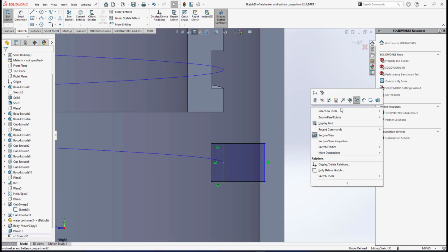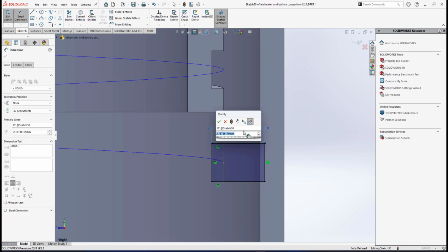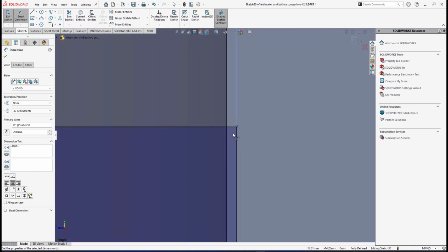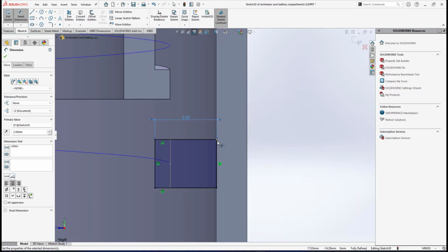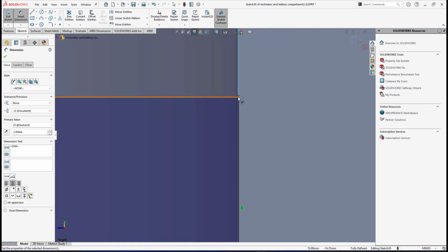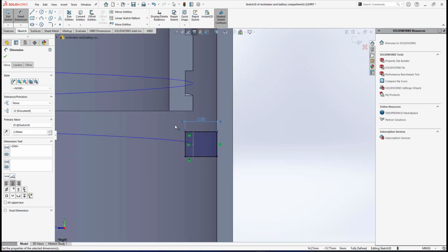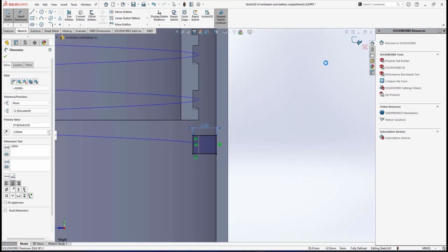All right, now I will give a dimension of 2. I go for 2 as it is a little bit over, so it cuts inside the thickness of the wall. You see this thickness of this casing, this water container. If I make it shorter than 2, we cannot produce the thread that I create using sweep. It cannot merge to this water container. So I make it a little bit over the limit here. So I make it 2. Okay, I exit the sketch.